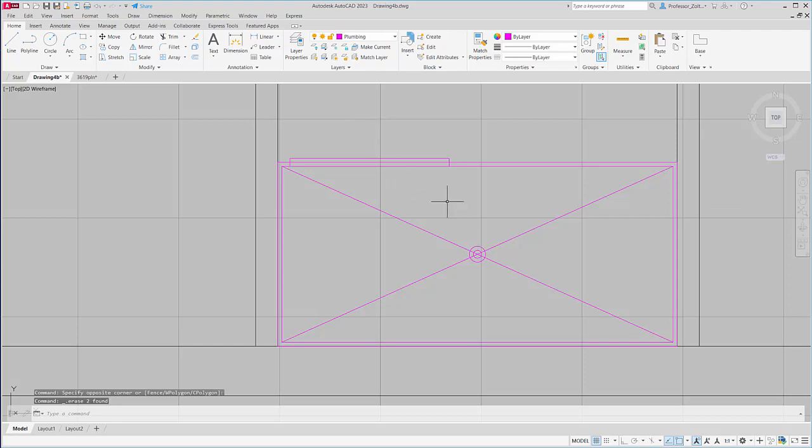Now I'm ready to create the door swing. Interestingly enough, again, it's a glass door which is fairly thin. I'm using the existing line work to create a rectangle, and then I'm going to rotate that rectangle around its pivot point 45 degrees. Now this is going counterclockwise, so it's positive, and then I'm going to make my arc.